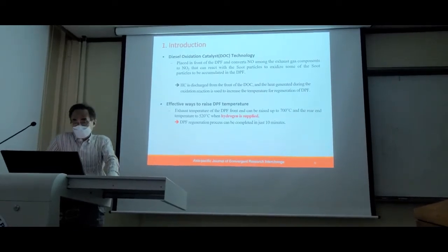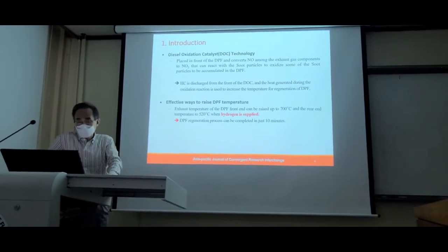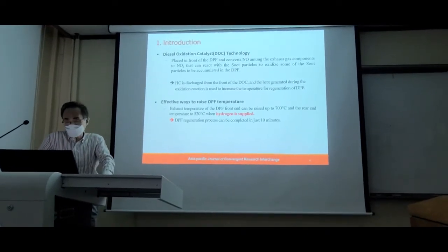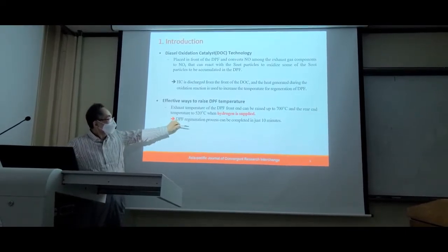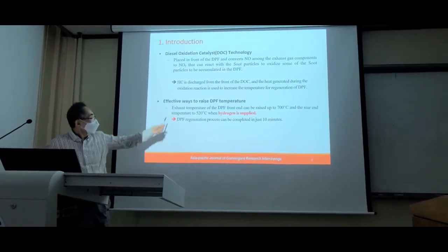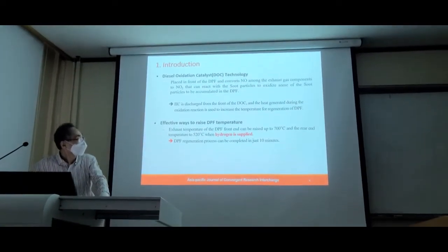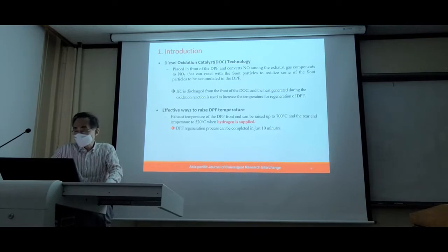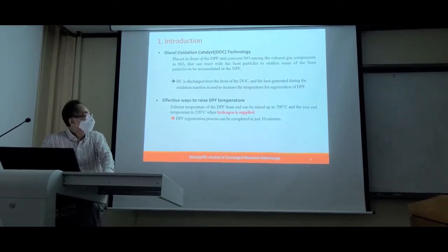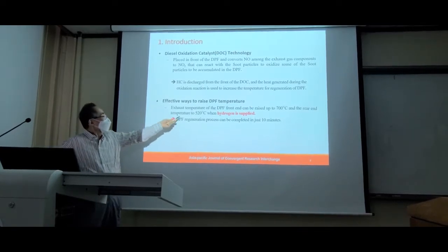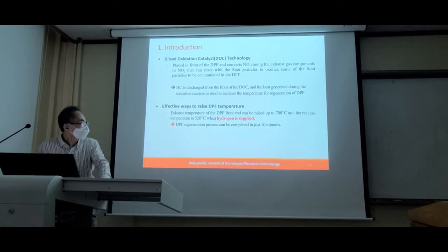So we have to mention about this one, the DPF temperature. This is very important for the DPF regeneration process. Because exhaust temperature at the DPF front can be raised up to 700 Celsius, and the rear temperature is 520 Celsius when hydrogen is supplied.